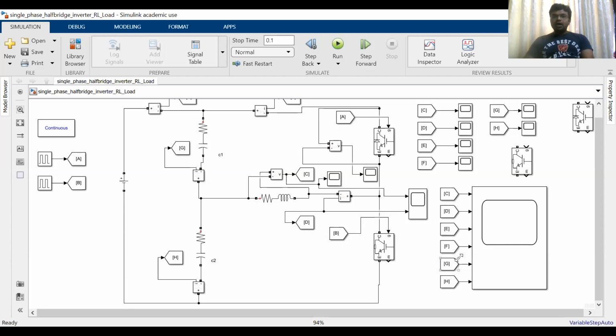Because if you are not discharging your inductor energy, then what happens? The current flowing through this switch is going to be 0, right? So suddenly you are making the current go from some maximum value to 0. That means the inductor is opposing sudden changes in current, which leads to a high voltage spike. Understand what I am saying, right?